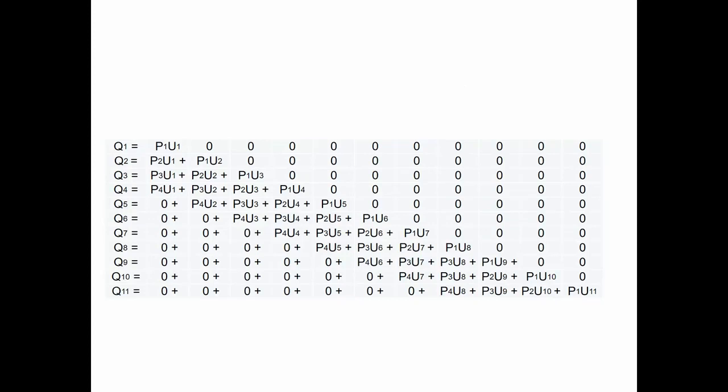This is another way of looking at our answer. You know the quantities during each hour, and this shows how the pulse makes its way through the watershed. By hour 5, we weren't seeing any more contribution from area 1, because area 1 had completely drained by time 5. But at time 5, there were other areas that were still contributing their flow to the outlet. So it shows the wave of water and where it's coming from at any given time: where was its original origin and what was its original time of contribution.